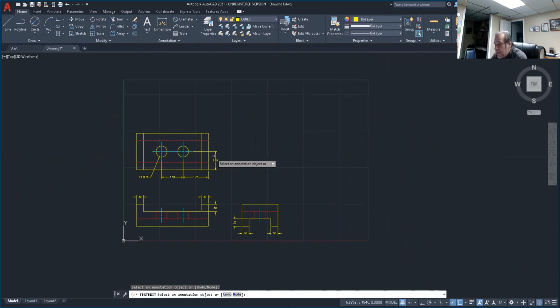drew it. Okay, now to finish this up, we have to put 3 more dimensions on the drawing. Our height, width, and depth. Now, where do we put our height, width, and depth? First of all, we could put our width right here, here, here, or here. That gives us all 5. So I already have dimensions here, so I would say either on top or on the bottom.